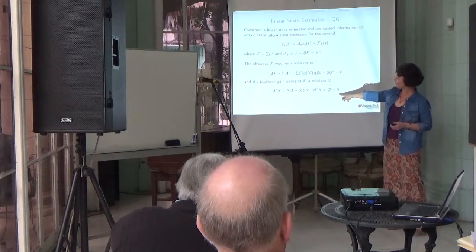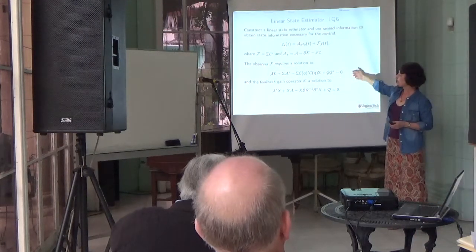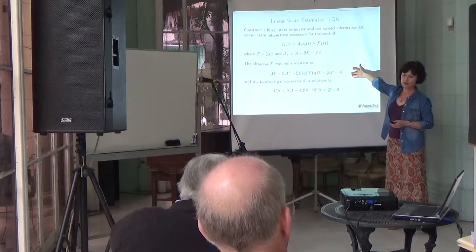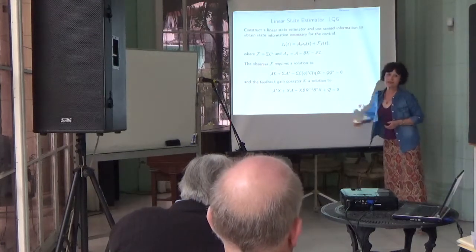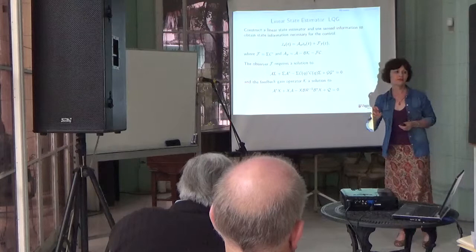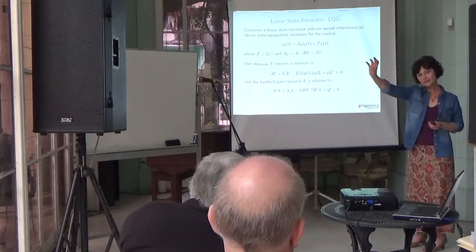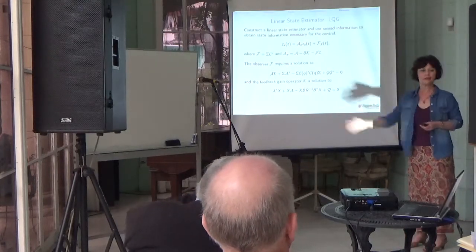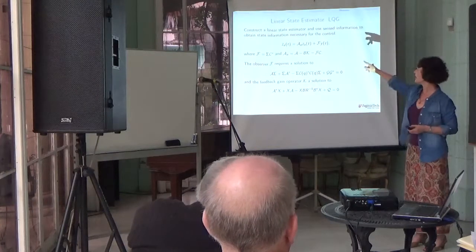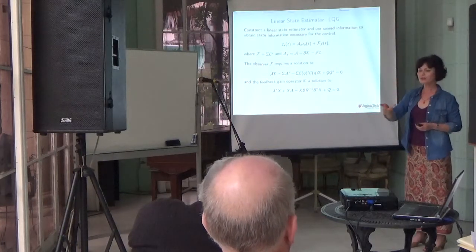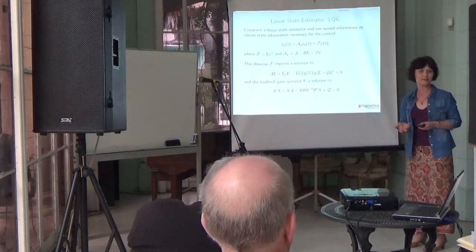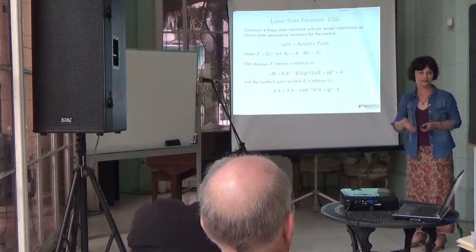The one from before to calculate K, and then an observer Riccati equation, where q represents the position of where I put the sensor. So for each sensor location, I have to solve an algebraic Riccati equation. I have my operators with appropriate initial conditions, and I have the state estimate. Calculate the controller and test the system.